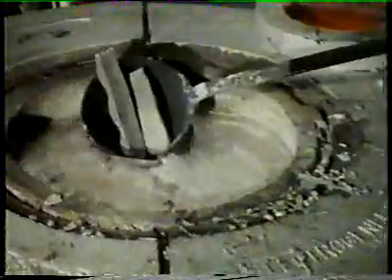First, we put into the molten aluminium a measured quantity of silicon. It's measured out by weight. After time, the silicon will dissolve. Then the magnesium can be added. We don't need anything like as much of this. Like the silicon, magnesium takes time to dissolve. This new material we formed is called an alloy. It's an alloy of aluminium.